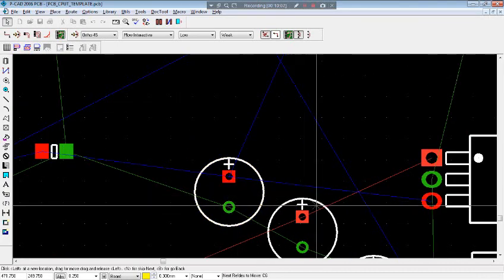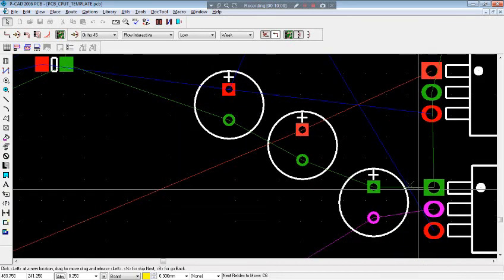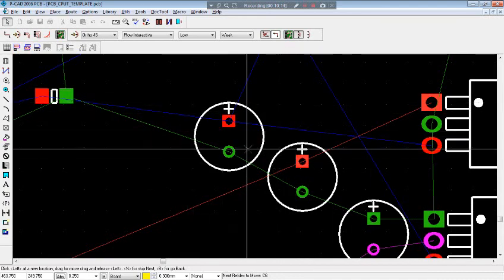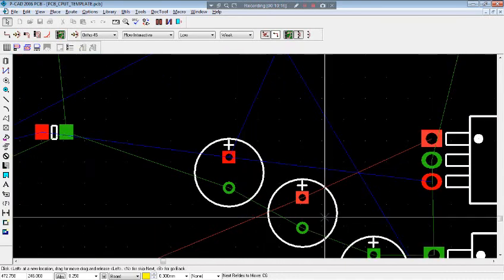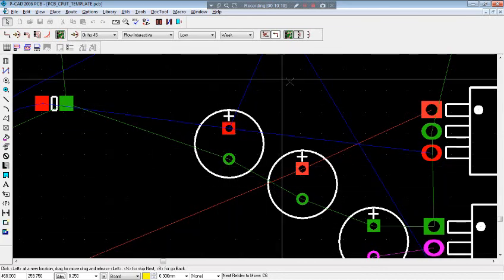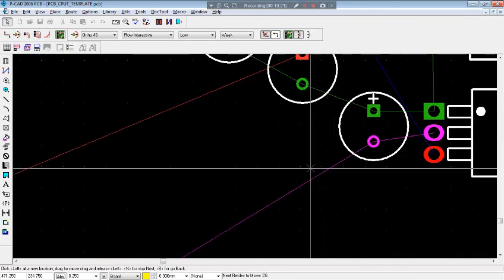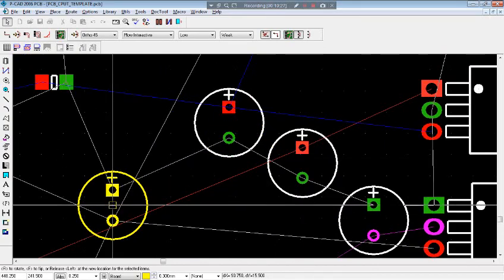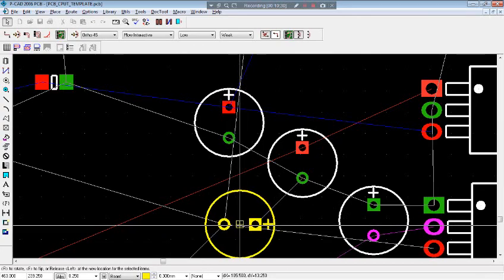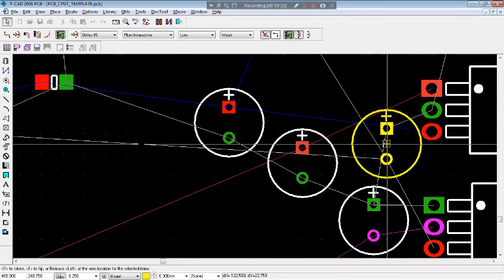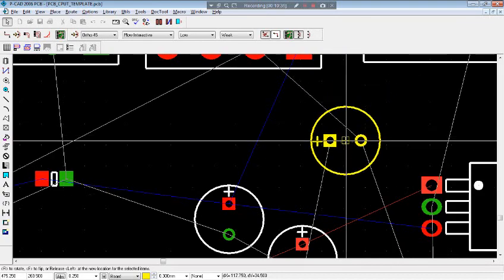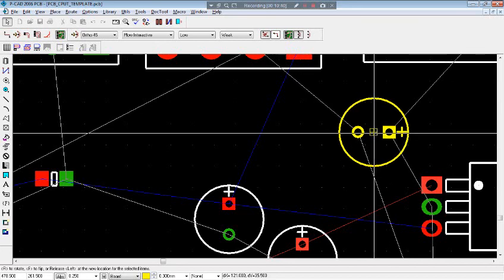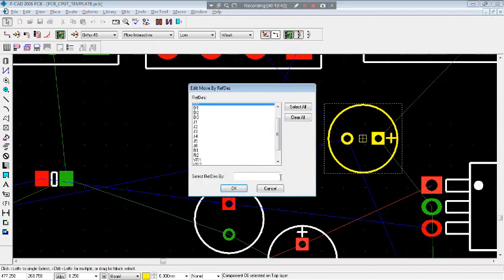Just a point of note, it doesn't matter if the wires are crossing now because these aren't actually your tracks on the PCB. We're placing everything in close proximity for now, placing it neatly, and then afterwards we can always move our wires wherever we want around the board. I'll show you that, so just make sure you're following. Place the next one. That looks okay, and that's done.